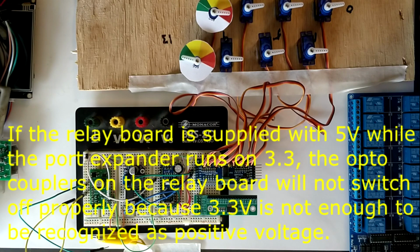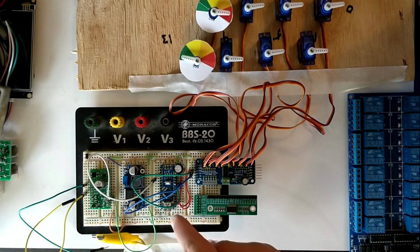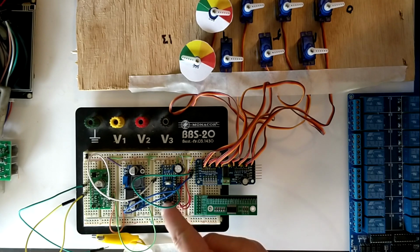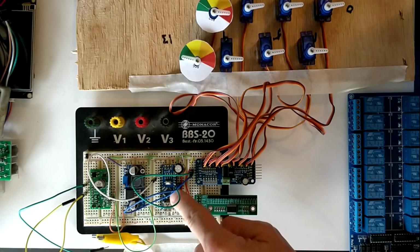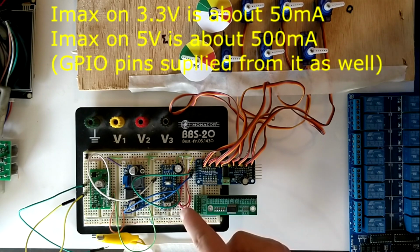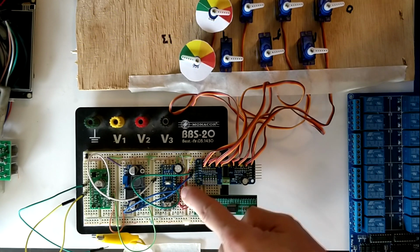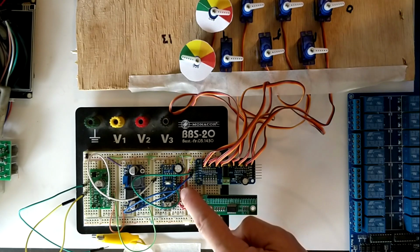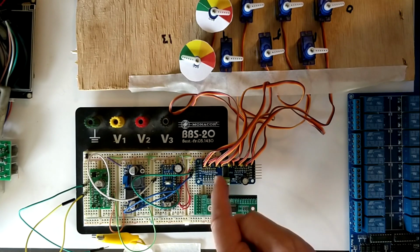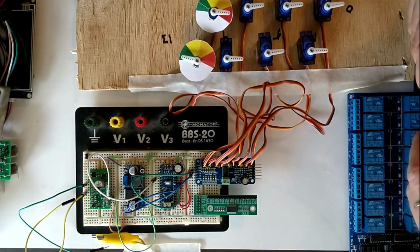And the reason I'm picking 5 volts is that the voltage regulator on the Arduino provides more output current on the 5 volt port than what is available on the 3.3 volt port. And since on the relay board we are using optocouplers that have a little bit higher power consumption than just a simple IC, I'm going to select the 5 volt.